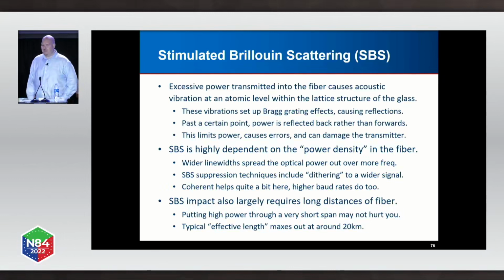And this is the stuff that you run across most commonly in your, well, I just took a 10 gig signal and I made it really bright, and why doesn't it work? Well, because of this. And modern signals, coherent signals, things that kind of dither the signal out over a wider spectrum, it helps, so it's not as big of a thing in a commercial, well-designed system, but it's very much the thing that you'll hit as you try to just take a signal and amplify it, and you haven't designed it properly. So SBS also requires long fiber.